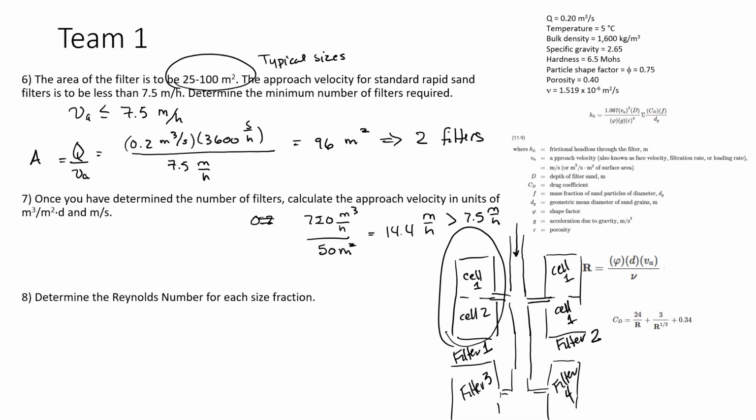Now the question is about a never-ending loop of particle buildup. The reason that doesn't happen is because of sedimentation. You're giving those particles another chance to settle in the sedimentation basin. If it weren't for that, you're absolutely right, there would be the potential for particle buildup. But sedimentation gives that second chance.